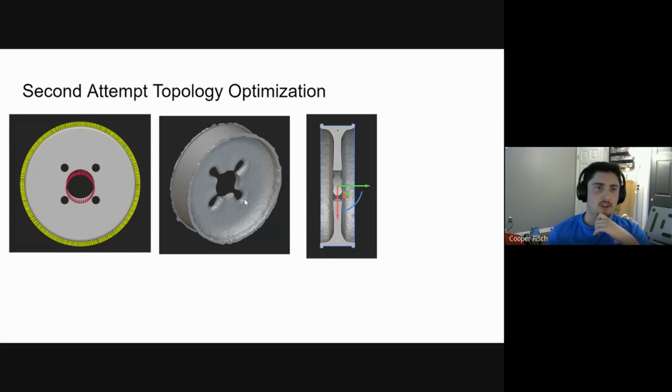So I add the volume constraint, but I also don't have the extrude constraint. And that gives us this sort of I shape, which makes some sense because if you think about things that bend and move, if you have a pure beam, the most stiff beam is going to be one where the material is further out, in this disc shape. Same with the wheel. If your pressure is coming here, you want a lot of material stacked there. And if you don't want it to bend, you need this kind of shape here. So this is a way more optimal design than what was before.